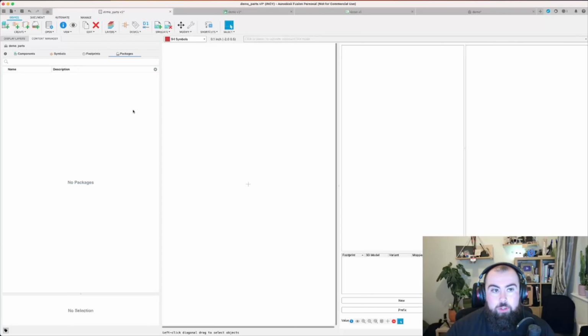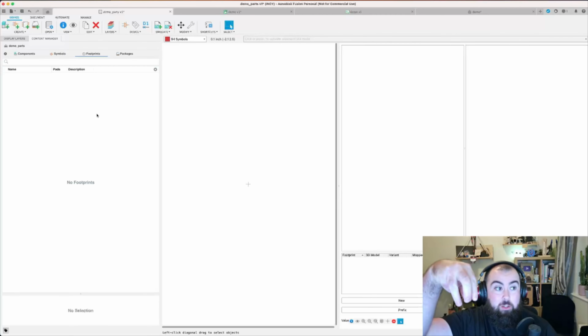They're not super important, but there's one thing that they're very important for in terms of your part library, and that is the footprints. Footprints are the layout of the pads that will actually go onto the board. It's called a footprint because your component sits down onto your board, and it will have little copper pads that it sits on. The dimensions of those are critically important because that's what your component gets soldered onto, so they need to be accurate. There is basically a relationship between the package and the footprint.